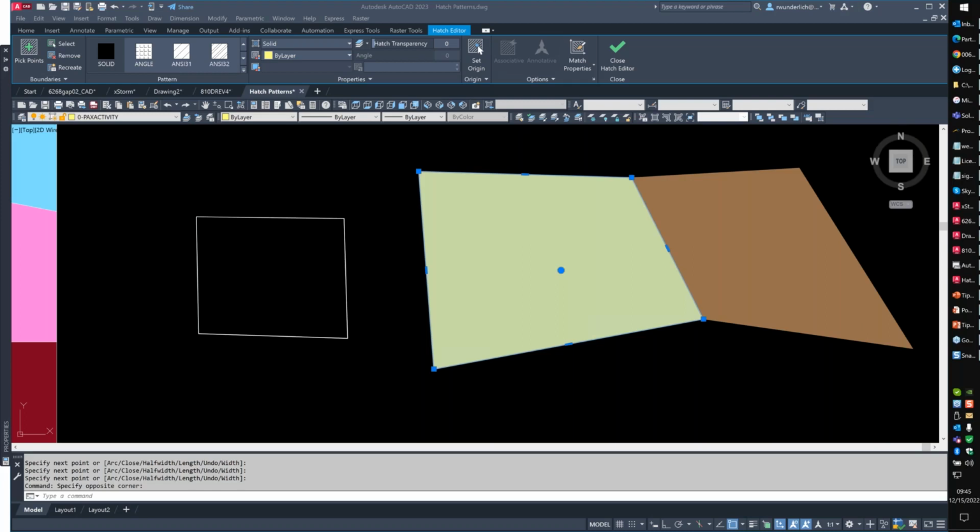Typically, when I create a standard library of blocks and details, I like it on a network drive. If not everyone can access that network drive, so let's say you have remote users over VPN, then I set up a login script that copies all those standard blocks and details to the local C drive. Any changes made on the network get copied back down on the next user's login, with an XCOPY looking for delta changes. You can run that as a batch file, and then you can set that up with a tool palette. You can use the block library.